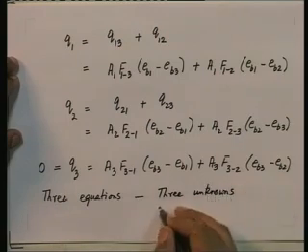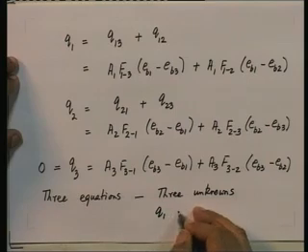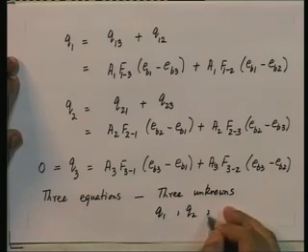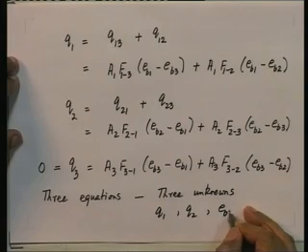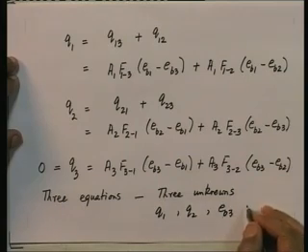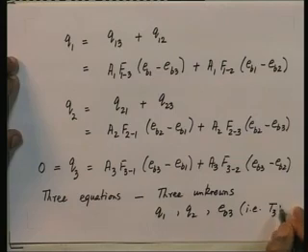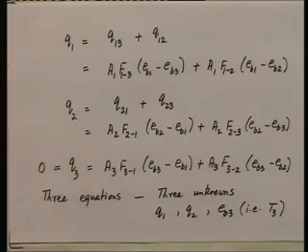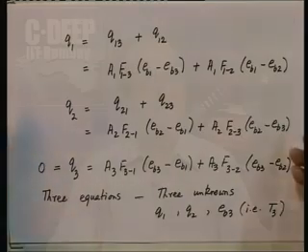And what are my 3 unknowns? Q1, Q2 and EB3. EB3 is nothing but sigma T3 to the power of 4; instead of writing sigma T3 to the power of 4, I am writing EB3. So, I have got 3 linear equations in 3 unknowns, solve for them, and I will get the quantities Q1, Q2 and EB3. So, it is a very straightforward problem which we have.